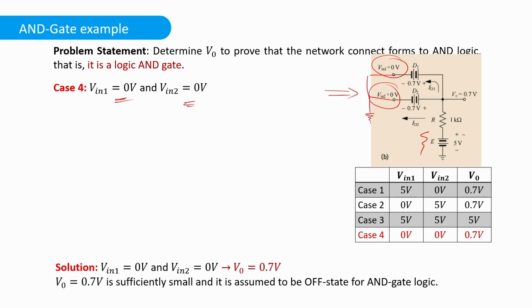So this positive terminal is actually connected with the positive terminal of this diode, right? There will be some power dissipated and voltage drop across this resistor. That's not a problem. But due to this positive terminal and these positive terminals, these diodes will be in forward bias condition. If they are in forward bias condition, we know that the voltage drop across diodes is 0.7 volts. Across the second diode, it will once again be 0.7 volts.